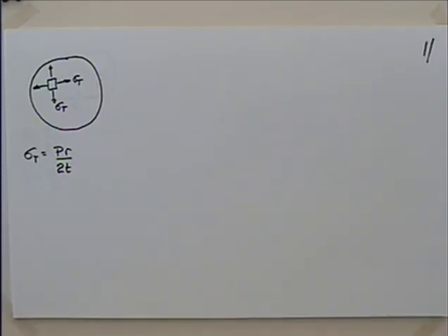You might say, well, is that the inside radius or the outside radius of the pressure vessel? Well, if it's thin-walled, it really shouldn't matter. It's not going to differ by that much. So the pressure times the radius divided by 2 times the thickness. And what I'd like to do is look at an element on the inside of the pressure vessel and an element on the outside of the pressure vessel.